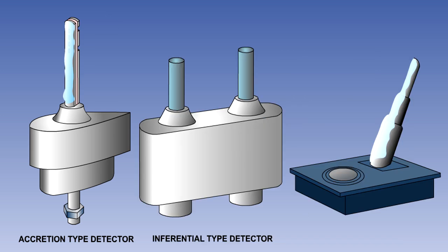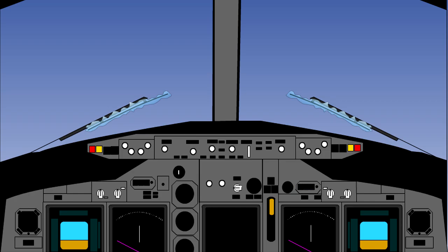You will find that on many modern aircraft there is no ice warning system, or perhaps just the Teddington type of visual indicator. So an awareness of the in-flight conditions with regard to temperature and moisture is essential for all aircrew. In icing conditions, the first signs of ice buildup can usually be spotted on aerials or on the windscreen wipers.